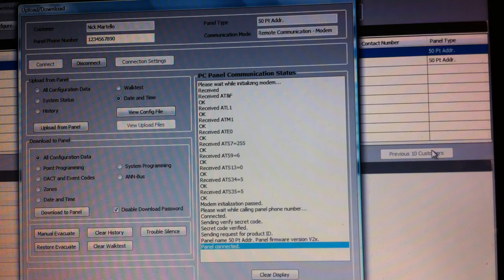And that's basically it. And once you're there, there's a number of things you can do. You can download history, which could take quite a while. Now, keep in mind what I said about the baud rates. The Firelight panels, to my knowledge, only support 9600 baud, and the UD port modem can support 56K baud. So it's going to depend on how fast your panel will respond. And typically they auto baud, so you don't have to worry about that. There's no baud rates to set anywhere. And that's pretty much it.